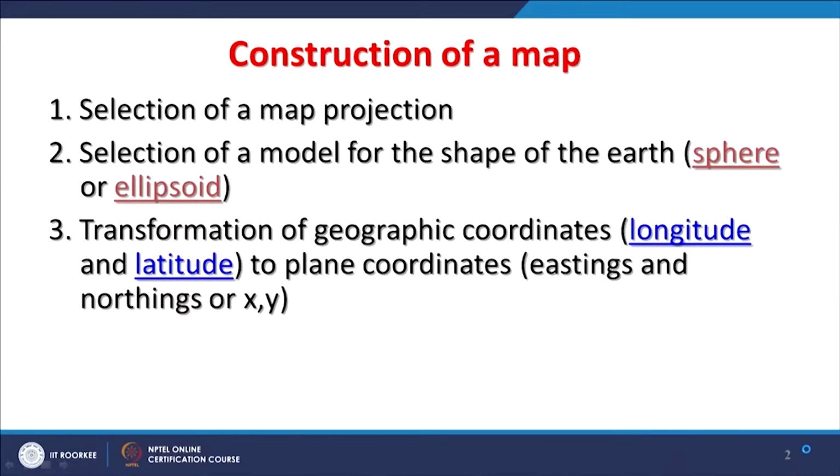Another issue is that GIS is very good at handling geographic coordinates in terms of DD or longitude and latitude, and the plane which we use for a map is flat. That means these curved lines have to be made straight lines on our maps, or a little curved, and therefore problems about accuracy of measurements will arise.